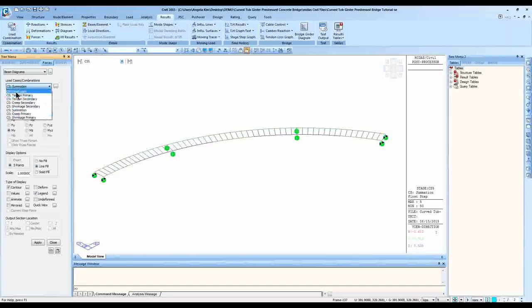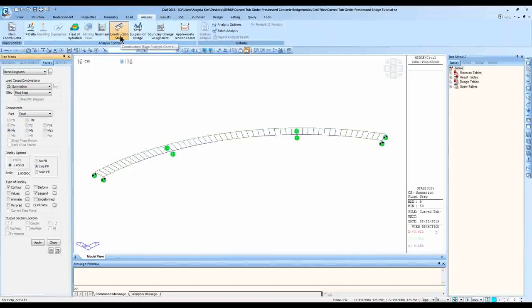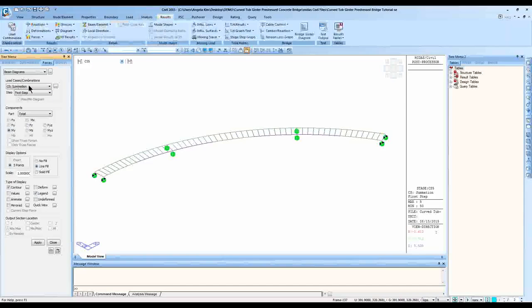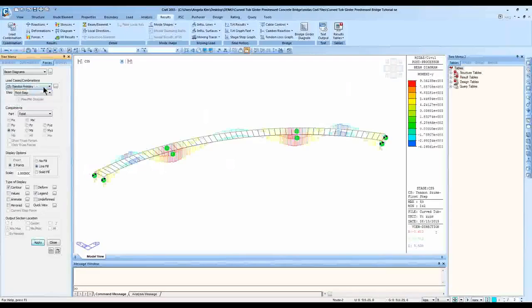And if you want to break down the dead load, you can actually go to analysis and go to construction stage for that and segment your dead load. Right now, anything that's not a part of tendon, creep, or shrinkage goes to the dead load. And I have a question come in regarding the moving load portion, but I'll get to it a little later. So basically, the tendon pre-stress result too, you can review just the same way you review the regular force and so on.